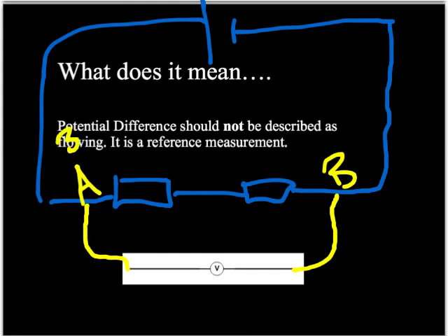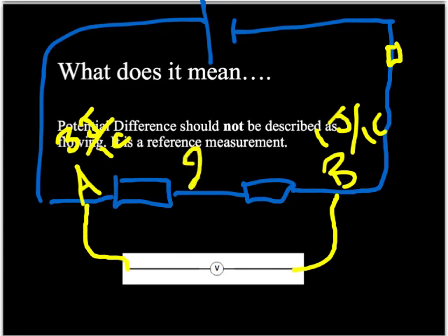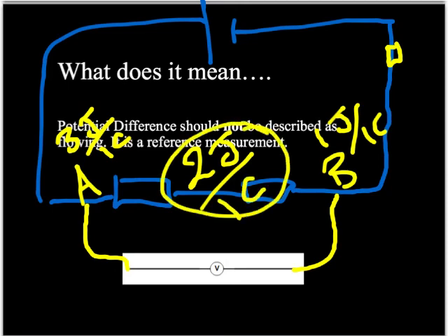So let's say there is 3 joules for every 1 coulomb there, and we have 1 joule for every 1 coulomb there. Should add another resistor to make it true. Then what is the difference? The difference is 2 joules for every 1 coulomb, which is the same as 2 volts. So it's used 2 joules for every 1 coulomb to get through that resistance.